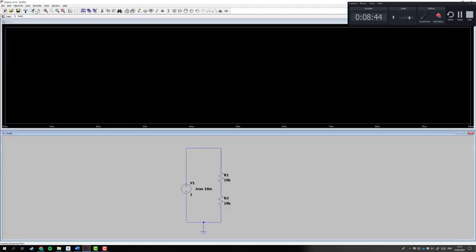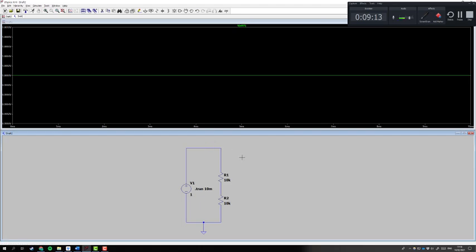So now we're going to run it, and we get this black screen and nothing. The reason for that is we've defined our simulation to be a transient simulation. If you look at the x-axis, it's 0 to 10 milliseconds, everything is there. The problem is we haven't defined our outputs. So let's define two outputs. First of all, let's define this line here. If you click on a line, you will get a voltage. And in this particular case, this is a fixed DC voltage, and over that entire time, we have got 1 volt, which is what you would expect.